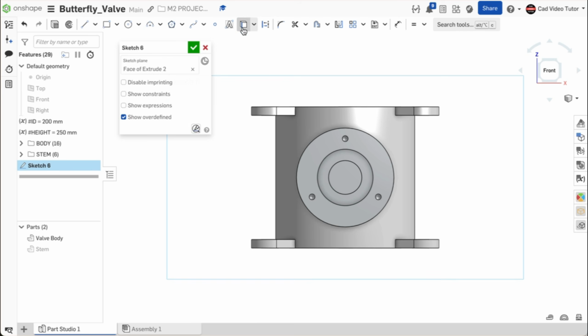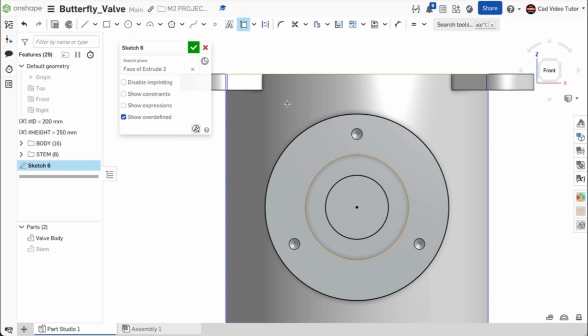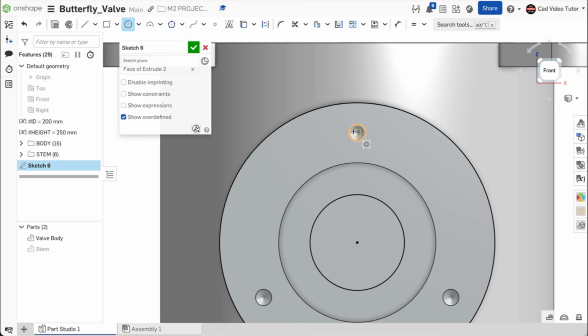From the sketch toolbar, click on the Use tool. Click on the center shaft hole to select it. Click on the outer edge of the boss to select it. We will now create the circles for the bolt clearance holes. Click on the center point circle from the sketch toolbar. Hover the mouse over the existing hole and look for the concentric constraint icon. Click to start the circle, make it a little larger than the existing hole and enter 14 for the diameter.